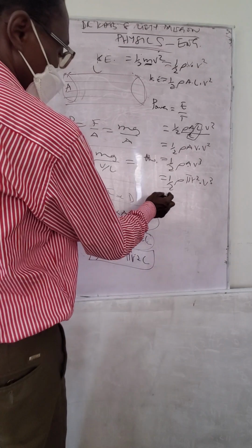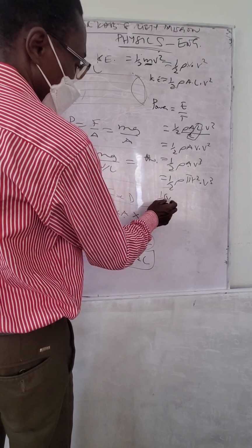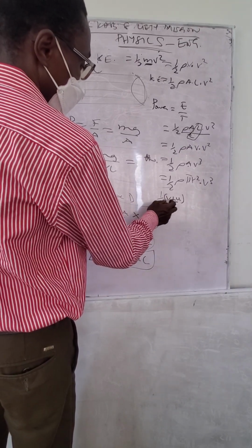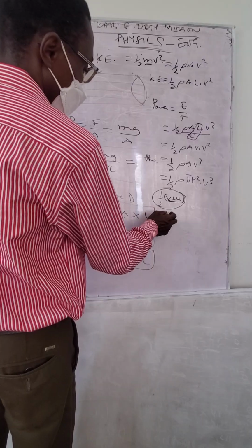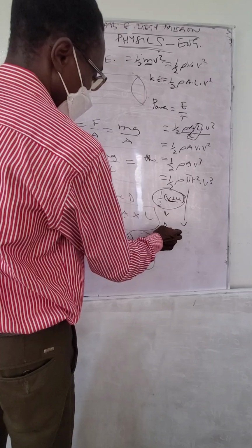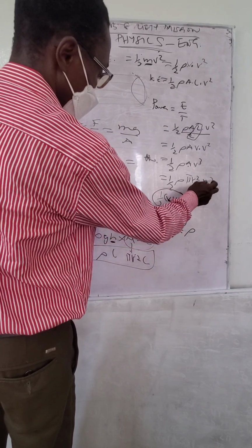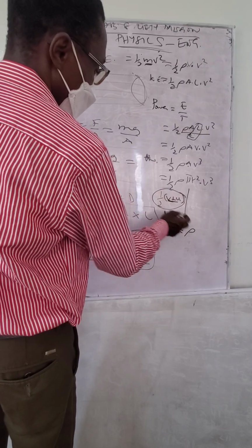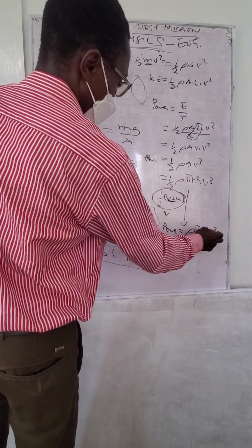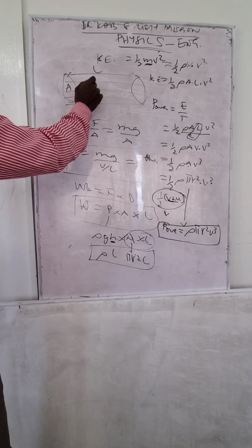Yeah, so remember this half we have here is because we have the average of the velocity v, whereas u. But if the velocity component is the same, 1v, then you don't need to find the average. So in that case, this equation will become what? Power is equal to what? Rho, because it's 1v, it's just the same. You are not going to find the average of the thing. So we have rho pi r squared v to the power 3 as the power for this moving column of air.